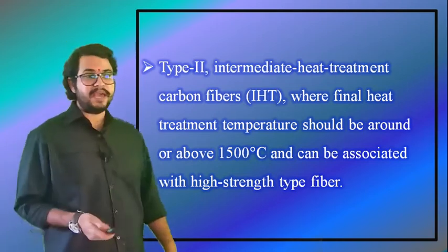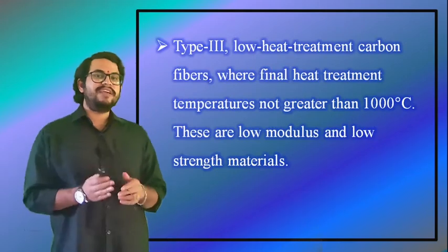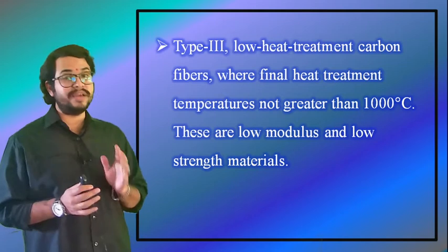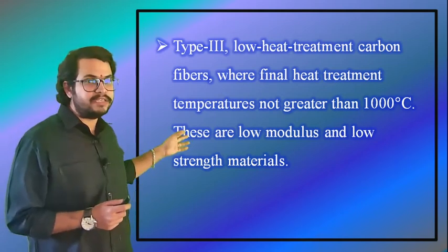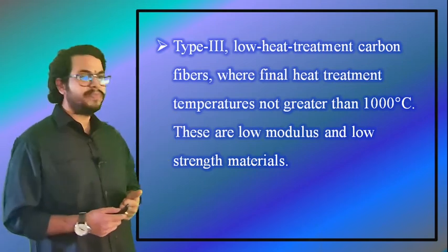Right? And the next we have is type 3, which is low heat treatment carbon fibers, where final heat treatment temperatures not greater than 1000 degrees centigrade are used. These are low modulus and low strength materials.